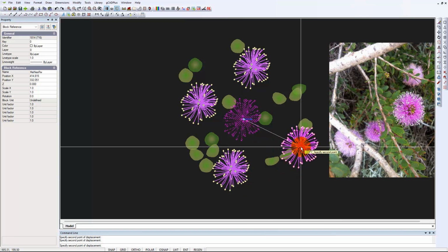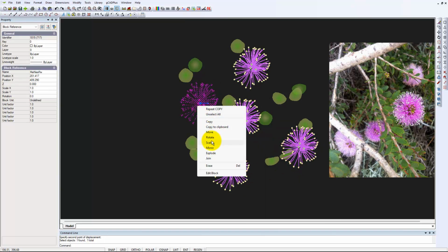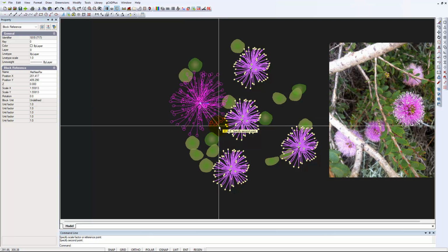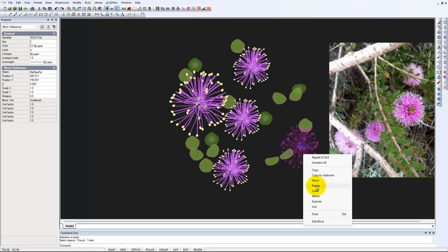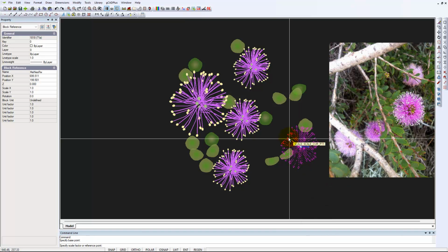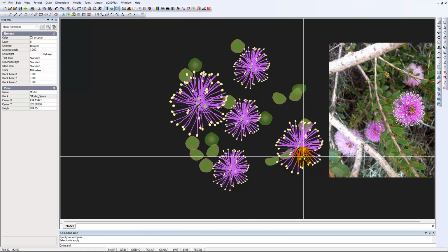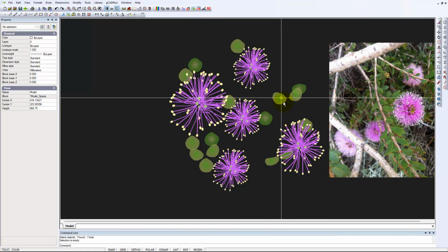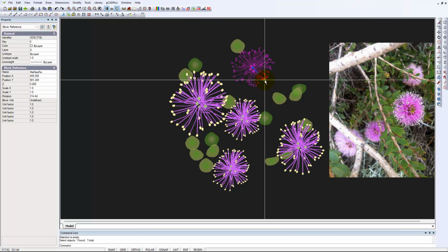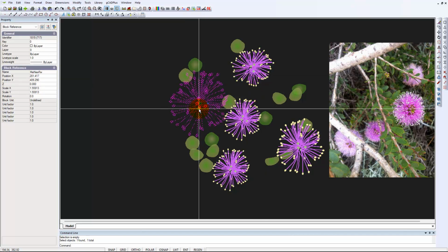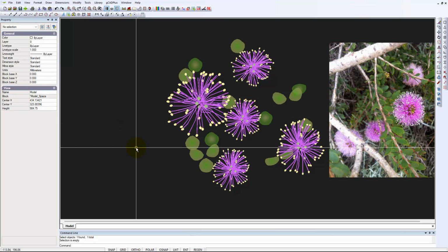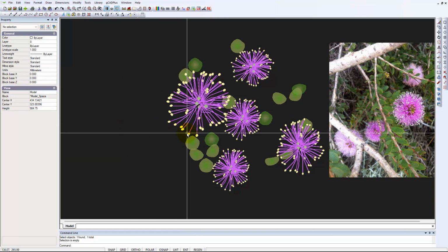and scatter them around, and we can scale them up, come out to the outside, pull different sizes, scale again, make that one a little better. It's a really good idea to rotate symbols, nested symbols within a block, and you could even give them a different X and Y scale. If we give that one an X of 1.7, I'll exaggerate a little. Can you see now it's sort of more squashed in the Y direction, so we could play around with it.